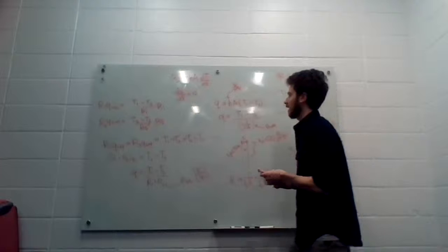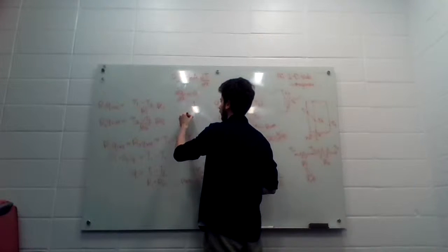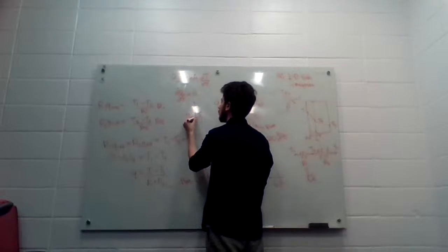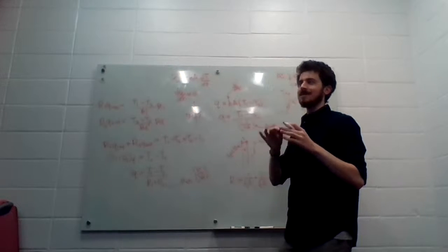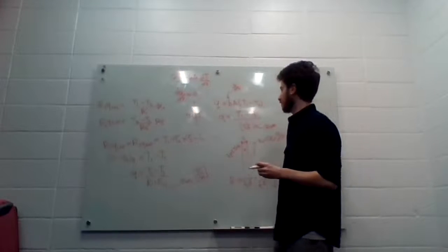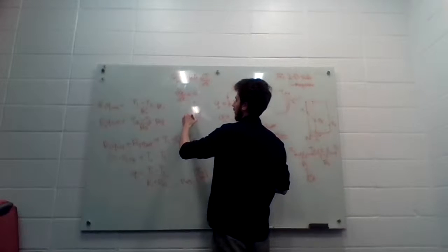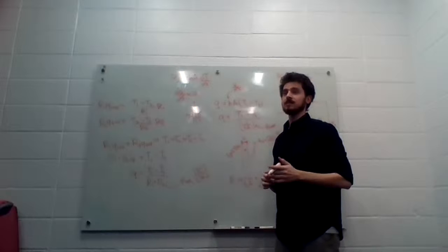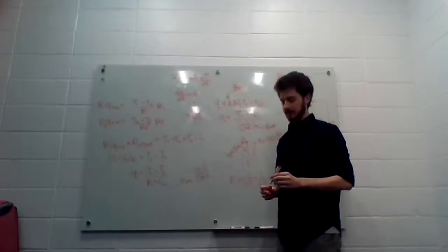If you had an aluminum wall and it was cold outside, and you said it was 20 degrees inside and 0 degrees outside, and you assumed these were the surface temperatures on either side of that sheet of aluminum, you would get completely unrealistic rates of heat transfer. When you factor in that there's an air barrier here, and this extra layer of thermal resistance created by convection, that really matters in this case. In other cases, it doesn't matter so much.